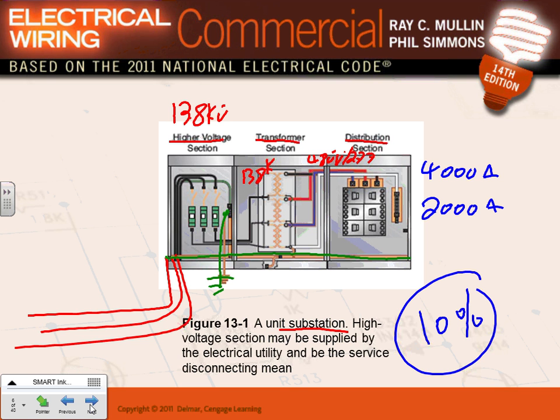When you came to the neutral, this is the primary side. The primary typically is delta. Can you guys see delta? The secondary typically is Y. So when you brought the Y, here's the Y, you bond this one to the ground. Can you guys see how it's bonding to the ground here? And the whole ground is going right here to Mother Earth. So you're bonding the neutral to the ground, right into the substation.